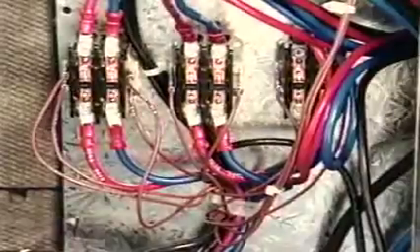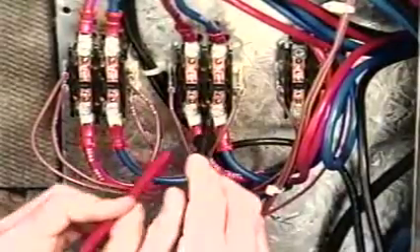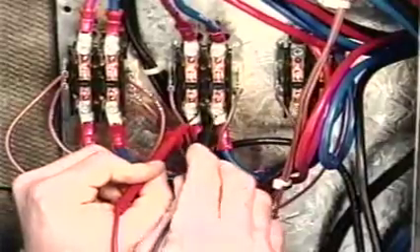The number 2 Relay Contactor is energized, but a voltage check at the supply indicates 0 voltage. Now you know why the second strip heater isn't being energized. There's no supply voltage at the relay contactor, and that means there must be an open somewhere in the heating bank circuit. The schematic shows that the supply voltage leg for each relay contactor is protected by a fuse at a central fuse block. To check the fuses, turn the disconnect off.